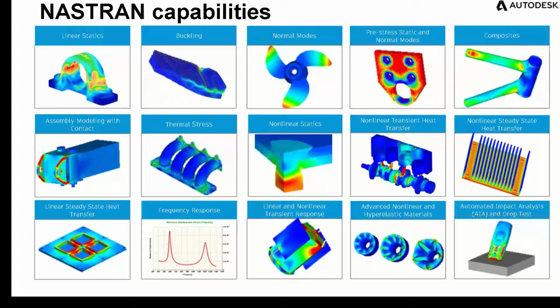The big hit with assembly modeling and contacts is that enforced stress that comes from another component. A lot of times we don't even think about that when we're just thinking about the piece part level. We don't realize how much stress from another component could be impacting our design. And that can be critical to find if that design is going to work or fail.